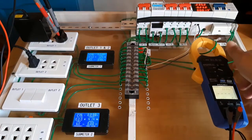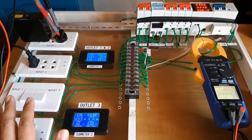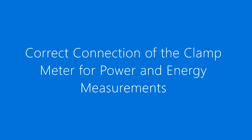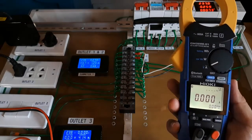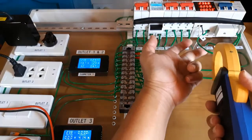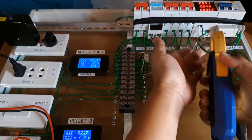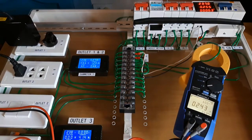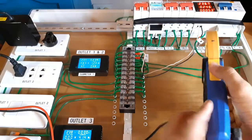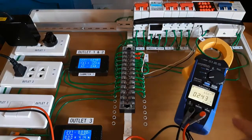When I put the clamp meter in this location here, it will measure all the current, all the power or energy going through all the outlets here. If I'm just measuring one quantity at any given time, like current only, and this is the conductor whose current I'm going to measure, the direction of the arrow at the clamp wouldn't really matter. I could point it toward the load, as indicated by that arrow on the conductor, and the instrument will measure current correctly. Or I can reverse the direction of the arrow in the clamp, and it will still correctly measure current.